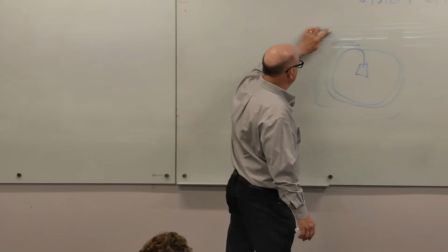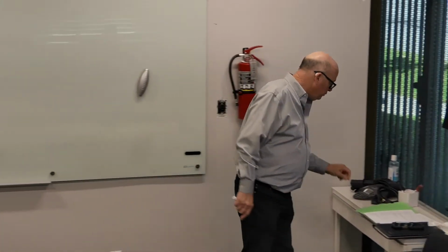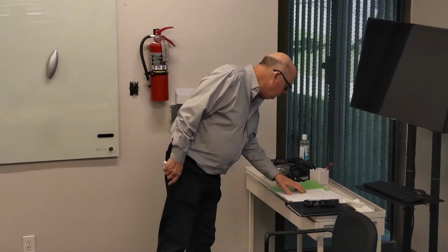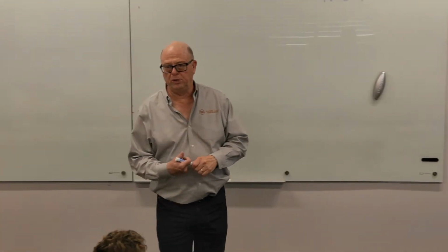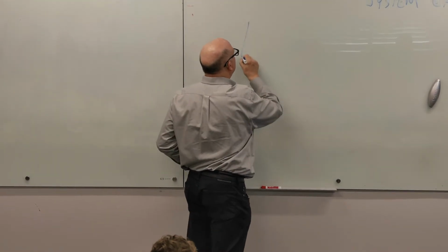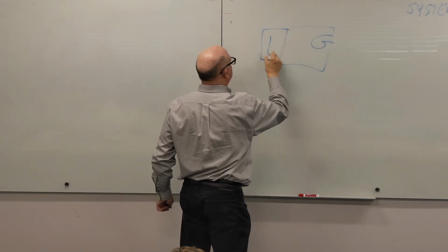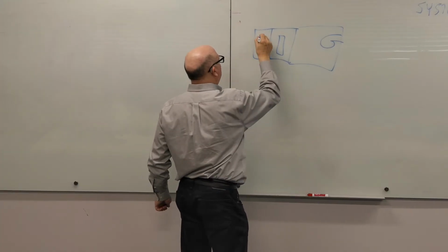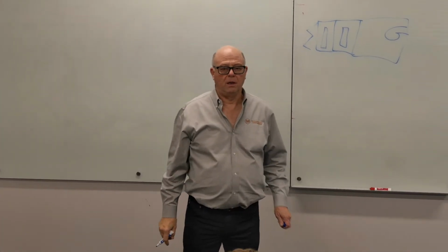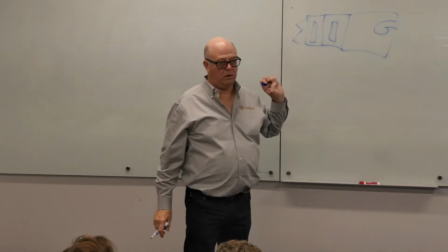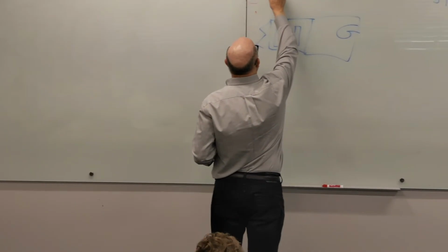Okay, so we talked about dual duct, we talked about mixing boxes, and we talked about dual duct VAV. Now let's spend some time on single duct VAV, because that's mostly what we do in commercial office buildings, or commercial buildings of all sorts. So I got a cooling coil, and I probably have a preheat coil, and I got a filter bank. If I don't have a preheat coil, and I don't have a DOAS, has everybody ever heard of a DOAS?